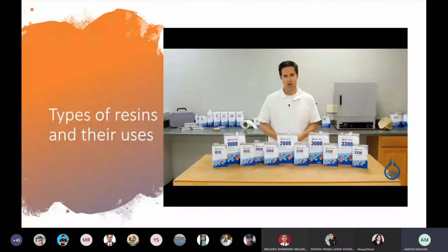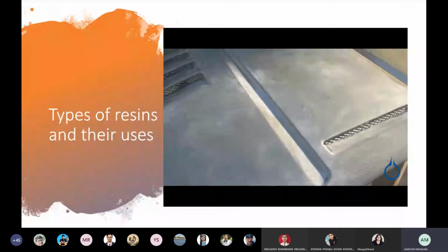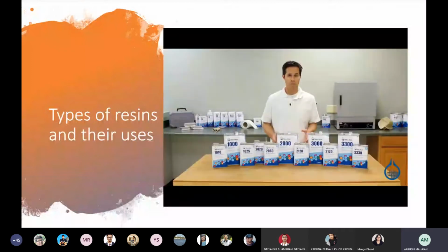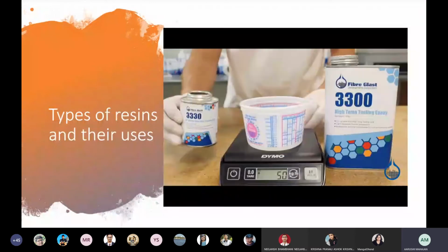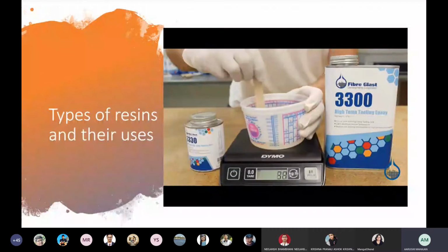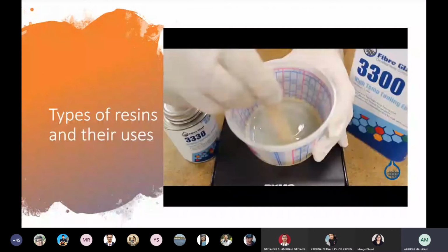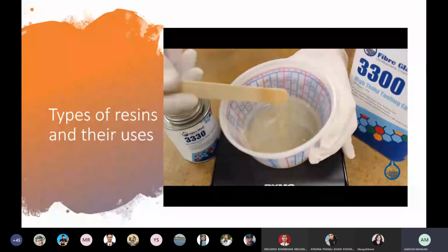Epoxy resins do have their drawbacks. These include being more expensive than polyester or vinyl ester resins and typically having longer cure times. Epoxy resins will also turn yellow and oxidize when exposed to UV light, including sunlight. Due to their mix ratios and the precision required when measuring, they are typically considered more difficult to work with than polyester or vinyl ester resins. Last, they also are more temperamental when it comes to moisture and temperature variations during mixing and application. If you are working in a high humidity environment, you will probably have problems getting your epoxy resin to cure.